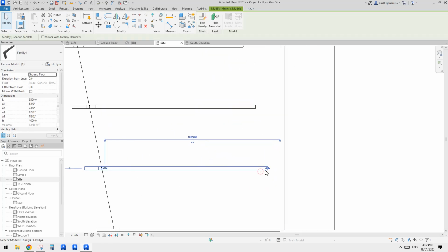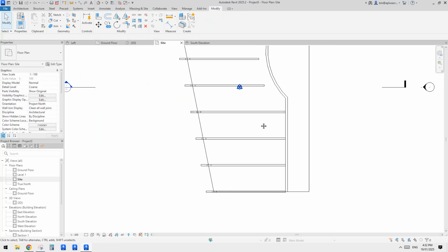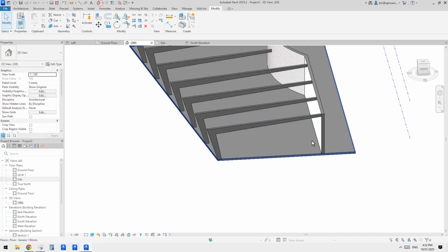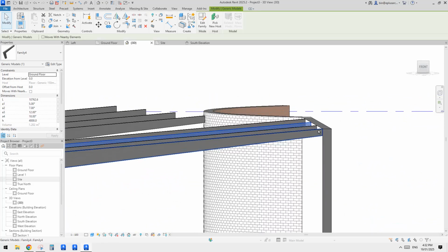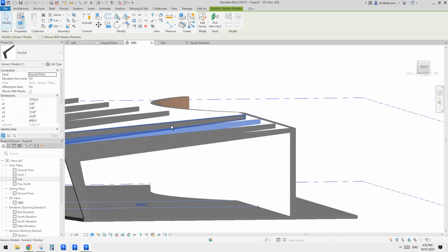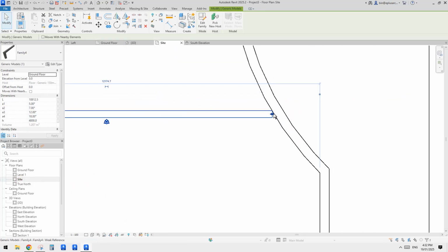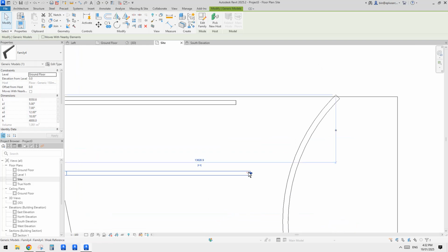So now we can just adjust the height to match this. But now we have some issue. Although we can adjust the length to match this roof, so let's go to 3D view. The height will be some issue because you can see currently they are all the same. So maybe I'll just finish this one. So I'll drag this to this, yeah, roughly to here. Drag this to here. So drag this and drag this.